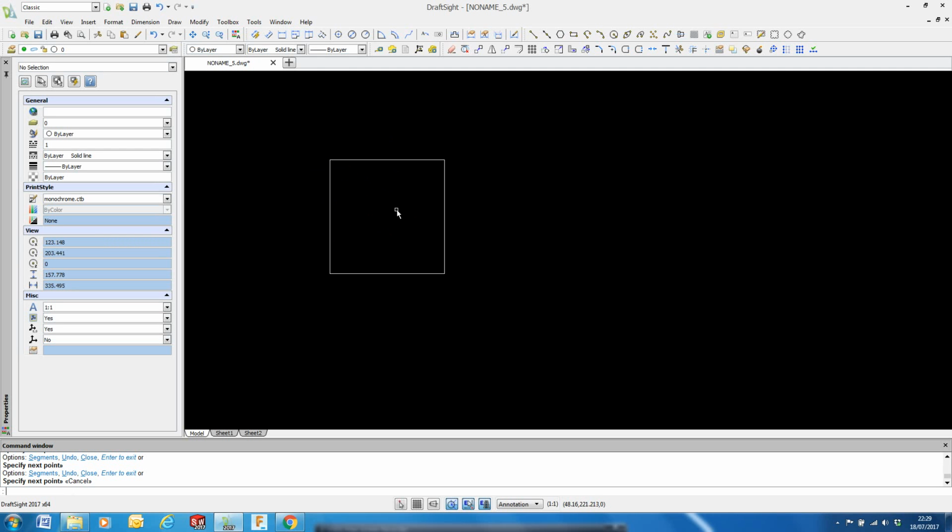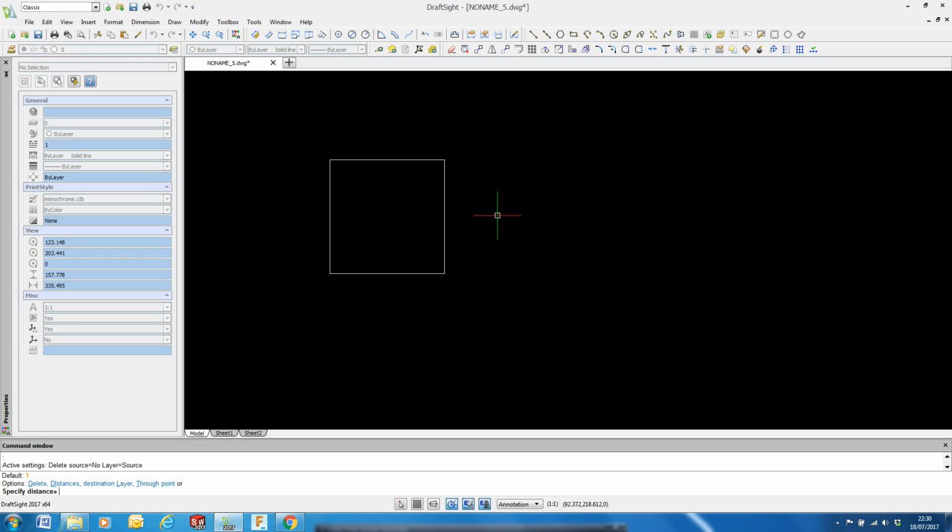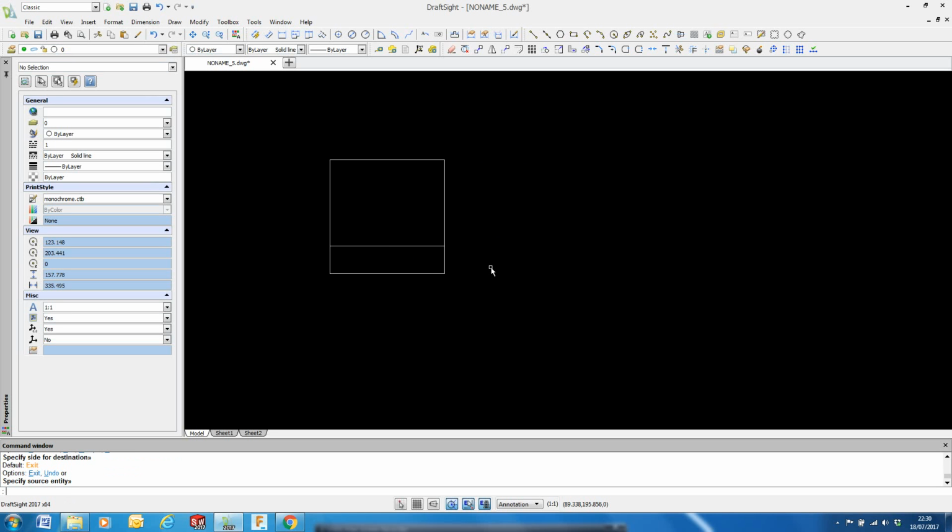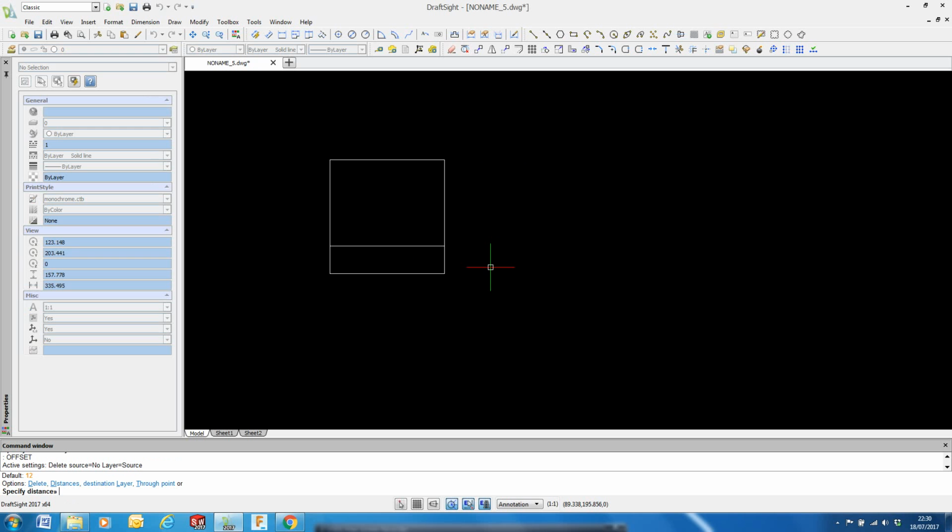So as my sort of side or front view, however we see it, I'm looking at the slot that goes across this face. So I can use my offset tool. My first offset is 12, and I'm going to take this piece there. I'm going to press the return key to close the tool, return key to restart the tool, new distance 15. And that gives me my total overall distance, 12 and 15, 27, which is the dimension on the drawing.